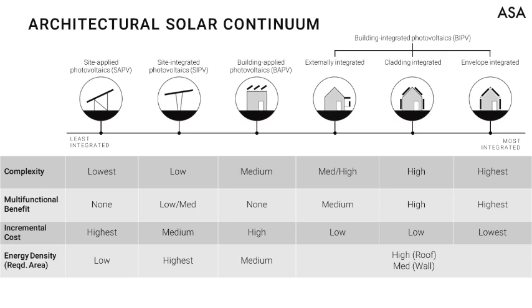On the left side of the spectrum, you have site-applied photovoltaics that are optimally oriented but require a fenced-off plot of land. On the right side of the spectrum, you have BIPV that is suboptimally oriented but shares space. Despite BIPV's efficiency shortfalls, it holds significant value that should never be overlooked from an energy density perspective. This concept may seem counterintuitive, but we will speak to it as we progress through our content.